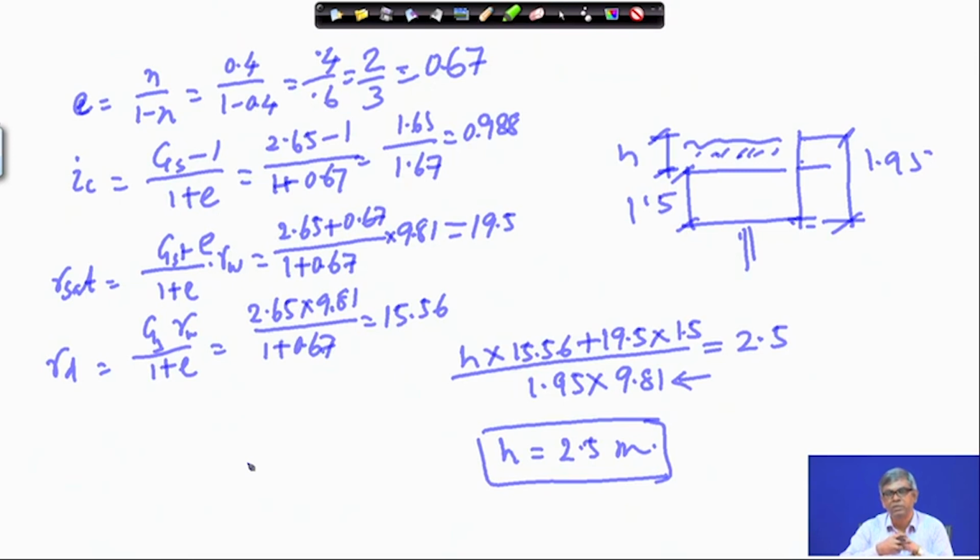Since I have not discussed the shear strength yet, I am not able to use that. Actually at the critical hydraulic gradient point, the soil loses shear strength, and because of that, if you put any load on it, it will not be able to support it. It will be like a flowing condition. That I will discuss again later on. So this is the second application, to achieve a particular factor of safety, and that is the application I have shown here.